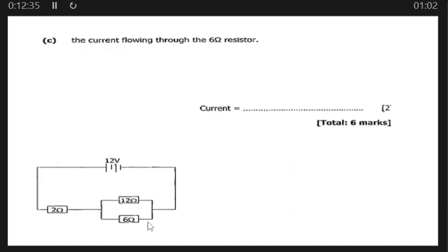And remember, in our lesson on a parallel circuit and series circuit, since this parallel arrangement is in series with these resistors, the voltage across this resistor here and these two in parallel is different.